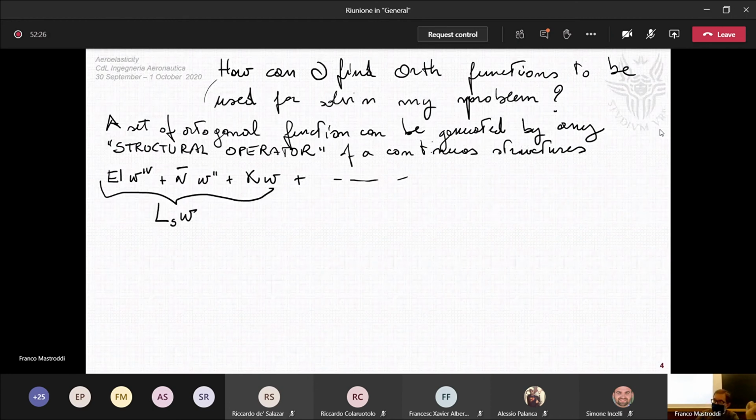You have the first term, which is the term of the elastic beam restoring its initial position. The second term is another elastic term related to the buckling membrane force, which is conservative, but please, before the buckling event, before the buckling. This force is conservative because it is generated by an external field of conservative force; buckling is a constant force in space. Last, we have our stiffness, K, which is another kind of conservative force. So, this is our operator.